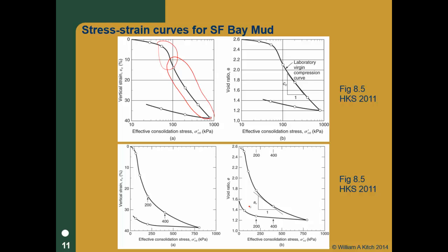And what does that material look like? Here's one thing I want to point out. If we were going to talk about this in traditional terms, we would call this sigma prime c, right? The pre-consolidation stress. And then what you probably heard was, well, that's the point where we pass the greatest stress the soil has ever seen, and suddenly it gets softer after that point because that's what was consolidated and unloaded, whether it was in the lab or in the field, right?